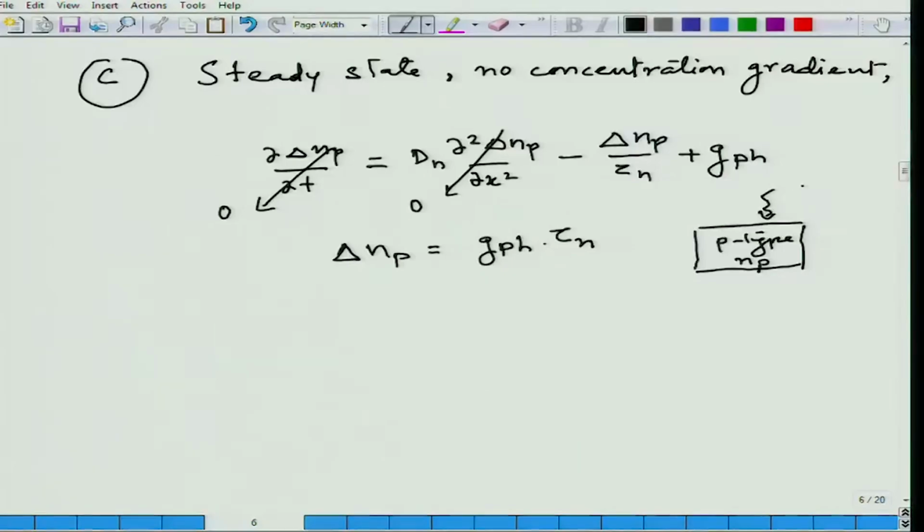It is creating certain electron and hole pairs at some rate per second, and I continue to shine. Eventually, the electron and hole concentration in the semiconductor will increase, that will increase the recombination rate for those carriers, and then it would eventually lead to a steady state. Hence, I say it is a steady state solution.